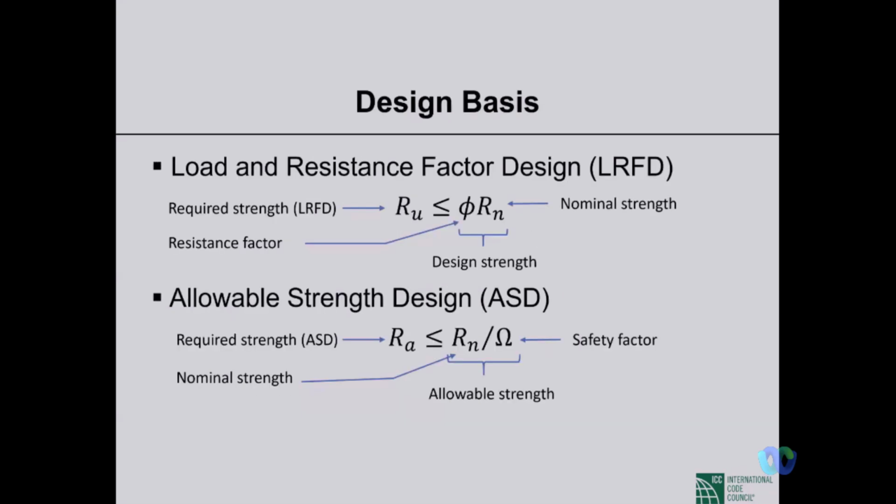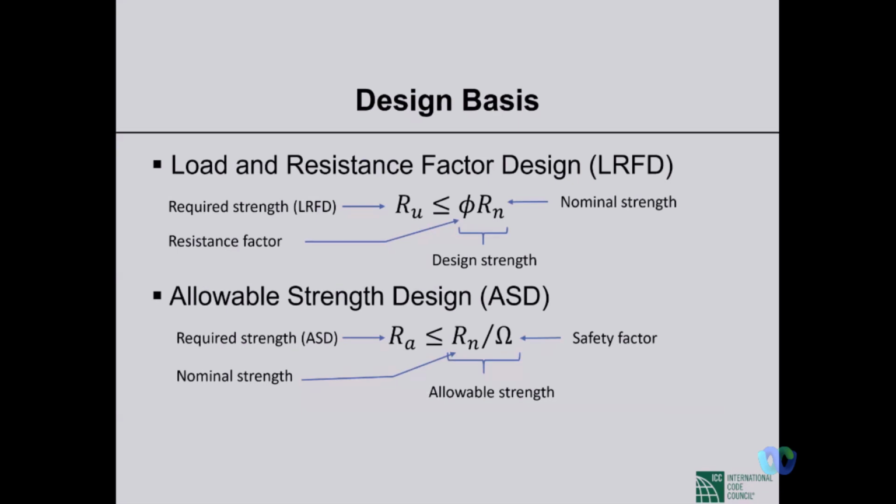So I've already mentioned about the design basis, that LRFD is the standard design basis now, which is load and resistance factor design, which is the ultimate limit state is considered in this case, although we design for serviceability too, but all the basic checks are in the ultimate limit state. So this is load and resistance factor design.